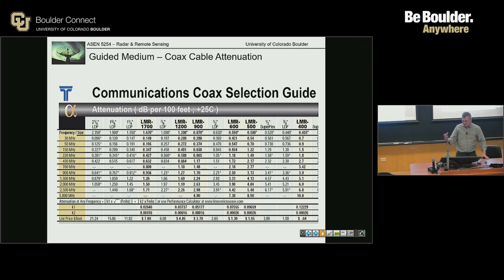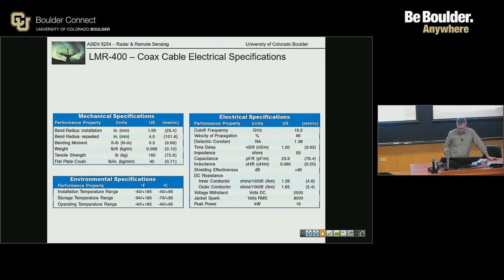And then this is just an example of how to read cables and the cost differences: you could pay more, have less loss, a bigger cable. How to look for these losses, what the trade-offs are. Propagation of the wave in your cable is different than in free space.